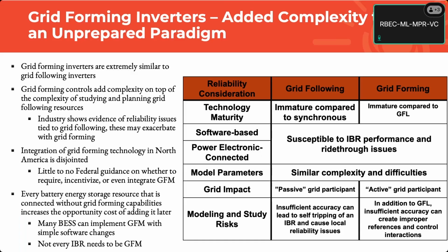A voltage and frequency reference. If you're 100% grid forming, then everyone's trying to shove the reference at each other, which means control interactions increase significantly. So somewhere in between, probably, a mix of grid forming and grid following is appropriate. People who have done studies like this in the past have shown about 30% grid forming is sufficient. But those are small island systems like Hawaii, and I'm sure the number is going to change based on your grid and its interconnected nature.